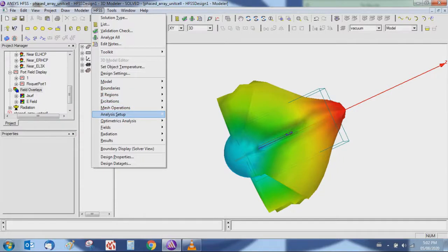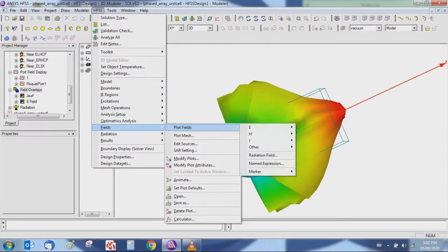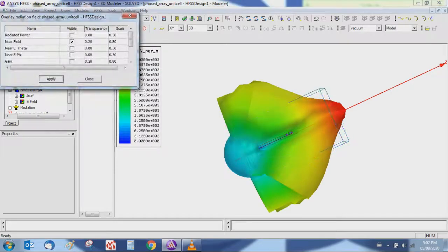The near-field region is the region right next to the antenna. Reactive near-field. In this region, the E-field and H-field are 90 degrees out of phase with each other and are therefore reactive. Radiative near-field. This is the region where the fields start to transition from reactive to radiating fields.